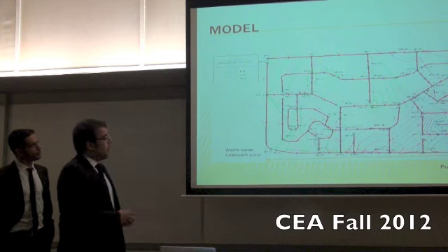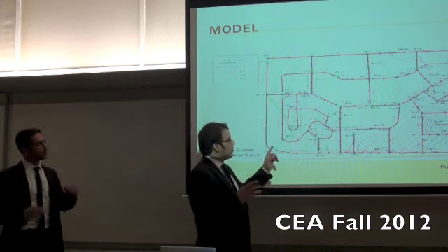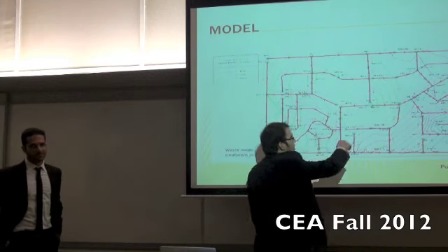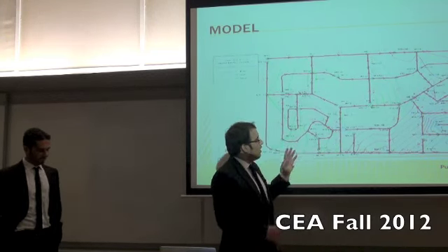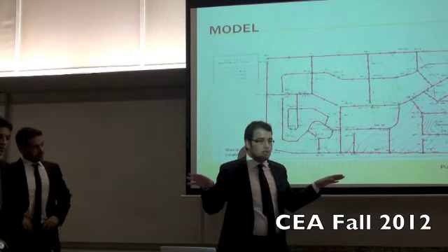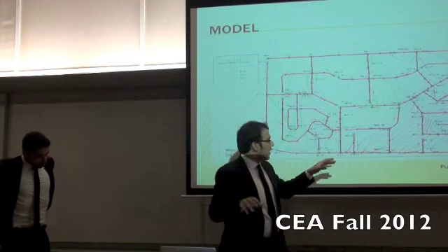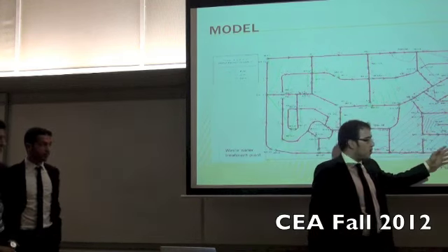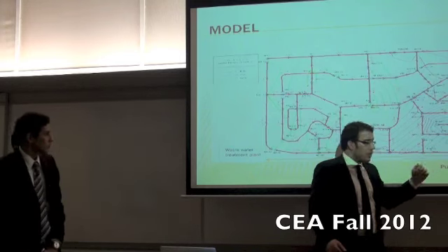Now this is our model. This model is with the contour lines to illustrate our modeling philosophy. At this point, as you can see, this is the highest elevation. Here we are restrained to use these dark manholes so that we can distribute the sewage by gravity. And at this point, it is the lowest point, and this is where we had to create our pumping station.